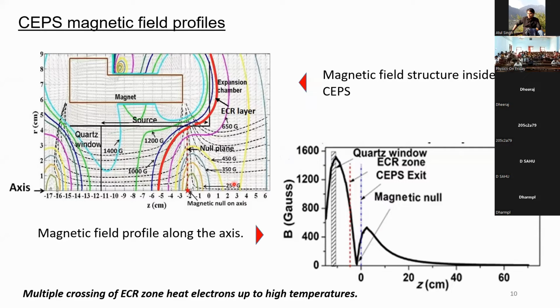So one of the advantages of the magnetic nozzle is that whatever plasma is inside, the electrons and ions can rotate along the field. So it can confine the plasma inside the magnetic field, and also it can take it out. Which means expansion by electrons: when the charged particle pressure inside the plasma is high, it will try to diffuse and flow outside. But here the field can also aid it in coming out of the system. That is what we want.